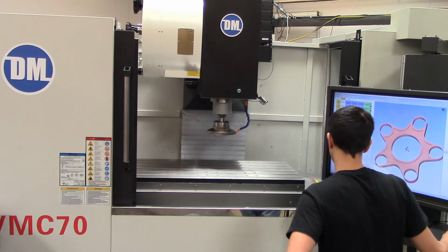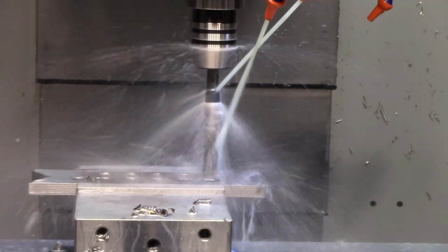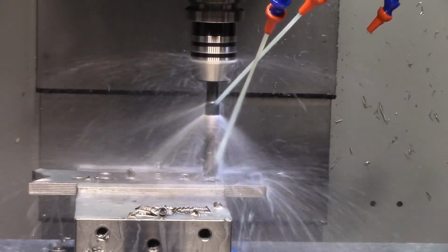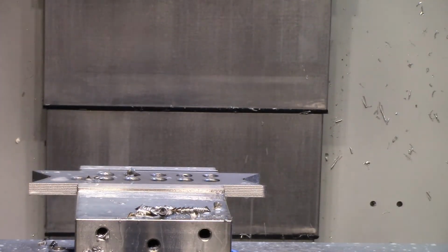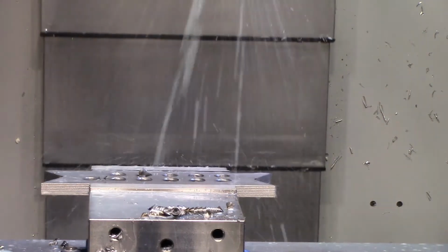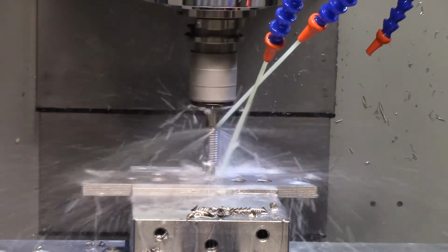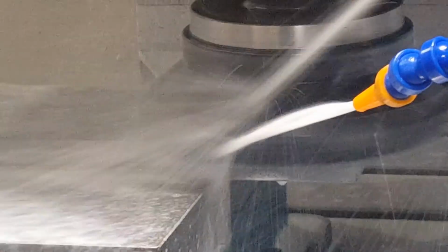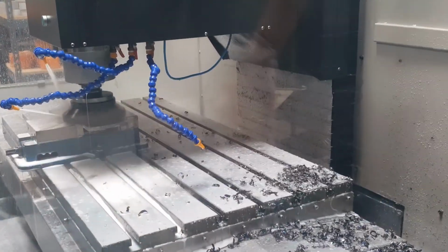Large tools like this 10-inch surfacer can be specified as a fixed pocket tool, which means they will always go back to the same pocket in the ATC drum. Once the tools are loaded up and lengths are set, the program will change tools automatically, as shown in this drill and tap program. High torque cutting works great, as shown here with this 10-inch surfacing tool. We're taking a full 1/4 inch depth cut in steel, which removes a lot of material quickly.